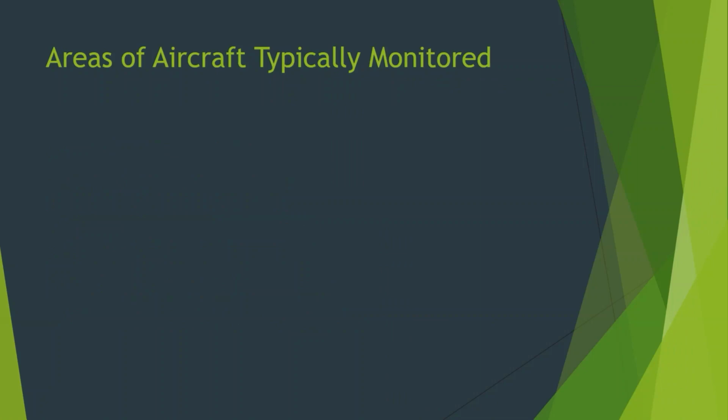So different areas on the airplane are monitored, but there's some standard areas that are normally monitored. For fire, areas that could have fire are areas where we have fuel sources, and it doesn't have to be jet fuel. Fuel can be hydraulic fluid, engine oil, cardboard, clothing and luggage, right? So areas where we have those fuel sources: engines obviously, hydraulic fluid and oil and fuel, and who knows what else. Cargo holds, right? You got all the stuff down there. People put their lithium ion batteries in their checked luggage, even though it says you're not supposed to, right?